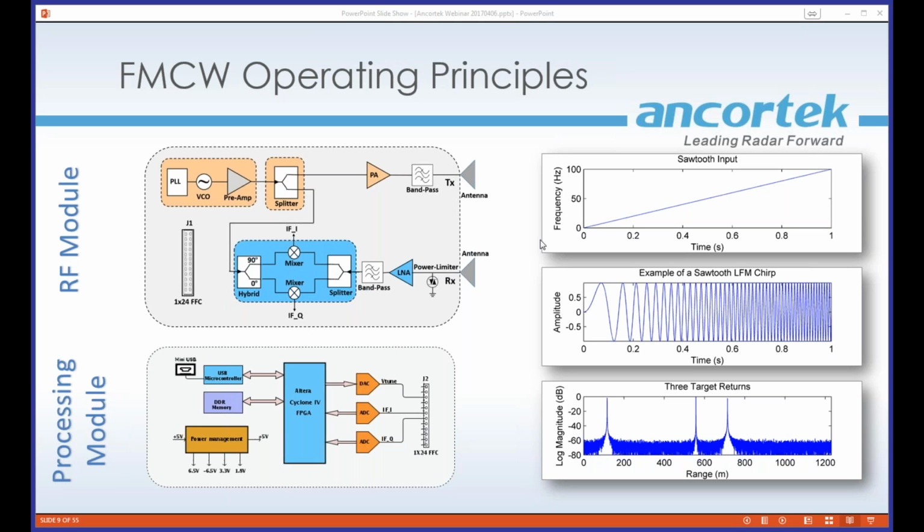All right, does it have a 10 megahertz reference input? That's from George Atkinson. Right now, no. This is something that we've been looking into because we want to do MIMO, or multiple units synced together. But right now, it doesn't. They all operate on their own. They all have an independent crystal that they use. So no, we don't have any kind of reference input for timing.